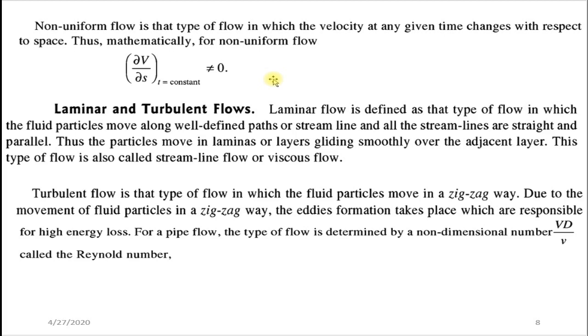In turbulent flow, the fluid particles will flow in a zigzag manner. There is no streamline in a turbulent flow. Due to the movement of the particles in a zigzag way, eddy formation takes place, which is responsible for high energy loss.